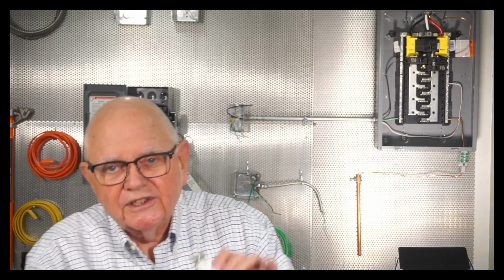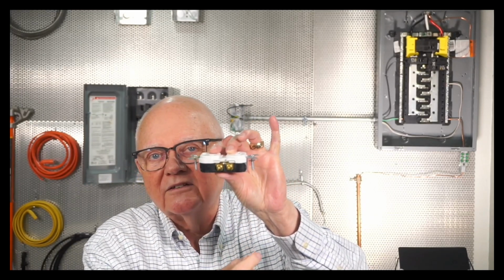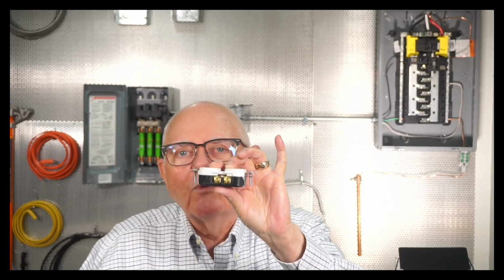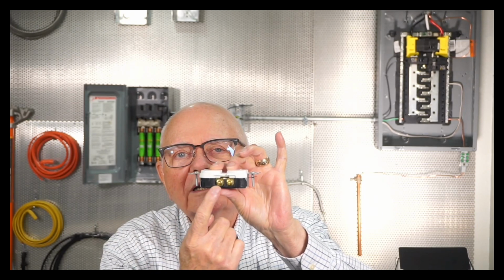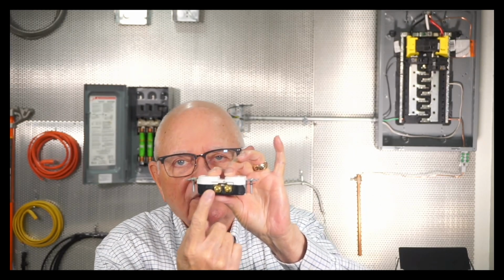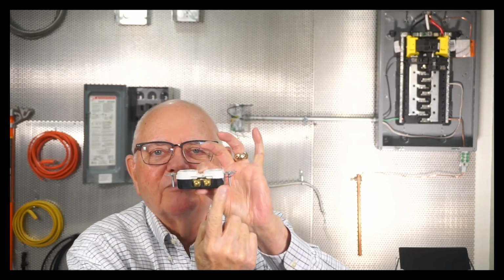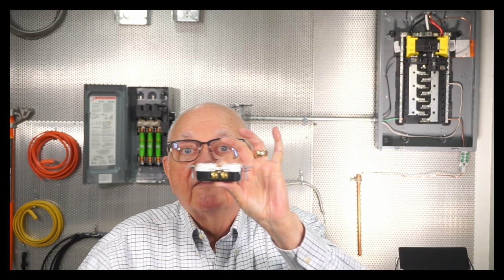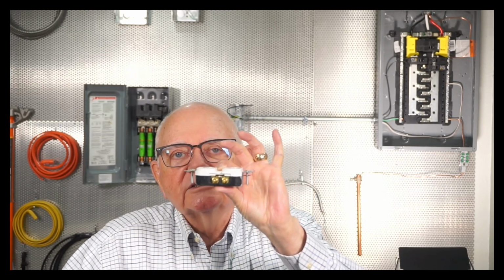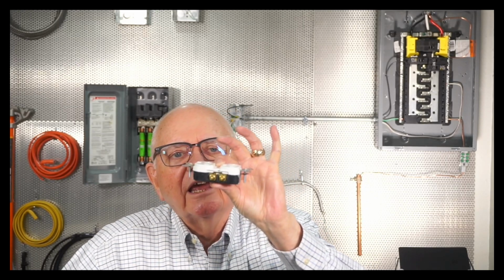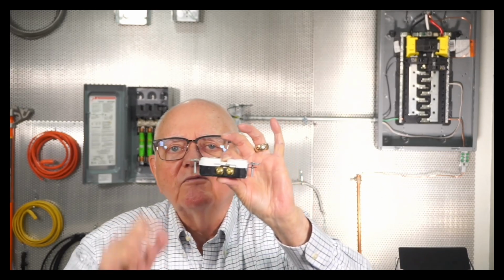Maybe not as common as it used to be, but on the multiwire branch circuit, I'm going to go to the ungrounded side on this receptacle and break off that little tab and separate out my two receptacles, right? So by definition, I'll run one conductor off of one circuit breaker to, say, the receptacle on your left, and then I'll run another wire to my receptacle on your right. There's going to be a voltage between those two sides of that receptacle, isn't there? The red and the black wire, most likely, in a dwelling unit application. And between that red and the black, I'm going to get 240 volts. So I have a line-to-line voltage difference there.